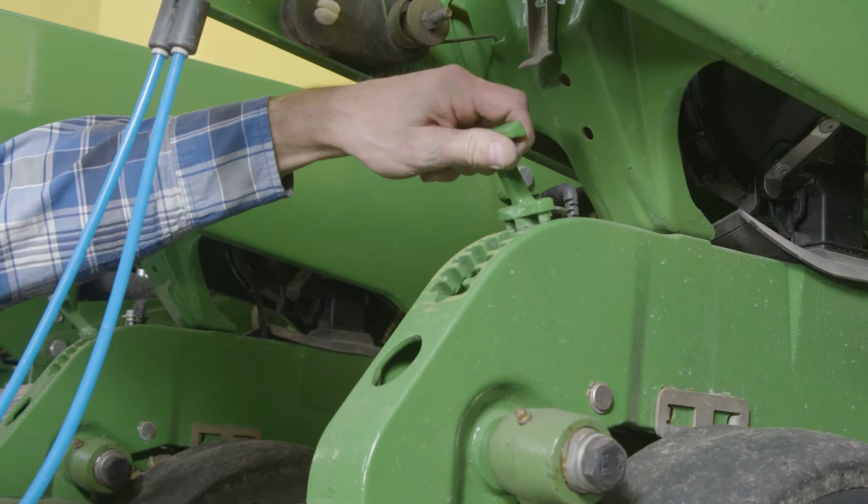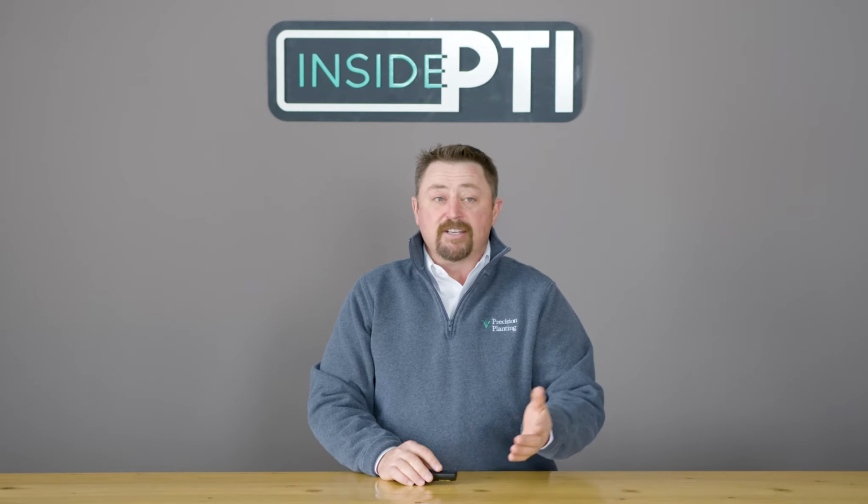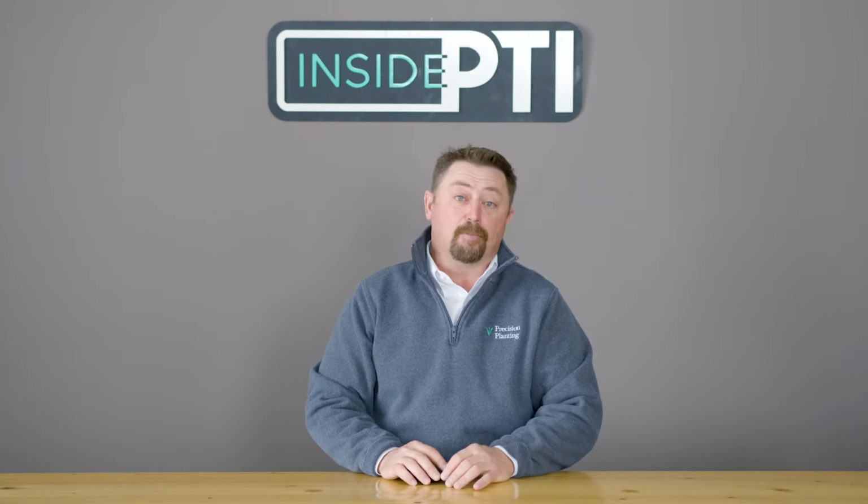Well, how do you change depth on the planter now? Well, we've got a T-handle on the back side of the planter, and we can grab that T-handle, we can move it up to plant shallower, and we can move it down to plant deeper. But it's been a manual, fixed setting in the past. And we've used this T-handle to put planting depth plots in.